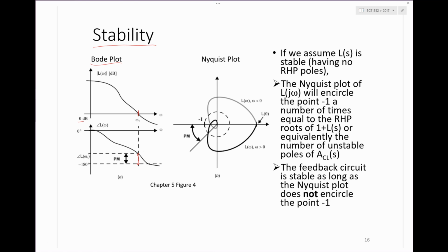But for more complicated feedback circuits, which I find are becoming more common in nanoscale CMOS technologies, where the intrinsic transistor gain, which we talked about before, is not that high. Because of that, people are having to use more transistors, basically more stages, in order to get a lot of gain.